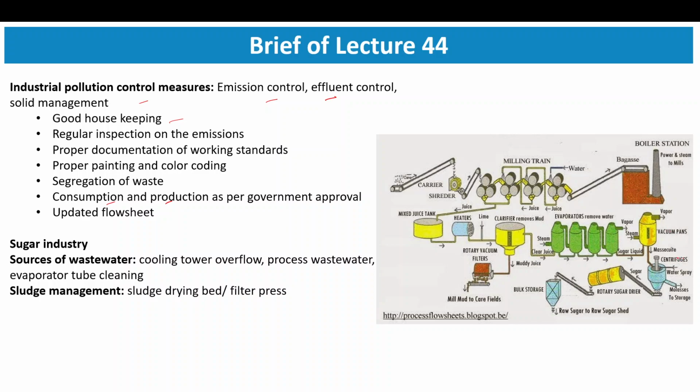Further concentration results in a greater quantity of sugar and less water, and sugar crystals are formed. The sugar crystals can then be recovered by passing them through a centrifuge, and later they can be dried in a dryer and collected.